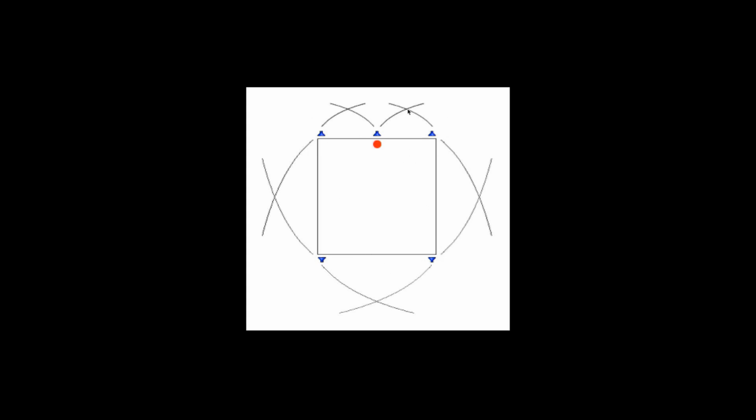And it's a little bit more interesting at the front, because we've got this additional center speaker here. So we have to treat the front like two stereo setups with a shared speaker, which is the center speaker. So we've got one equal power distribution from left to center and another equal power distribution from center to right. And if we choose the option of omitting the center speaker, this needs to switch to one standard panner from left to right with a phantom center with equal power distribution. So let's go check this out.